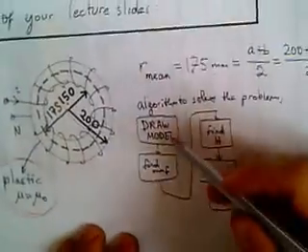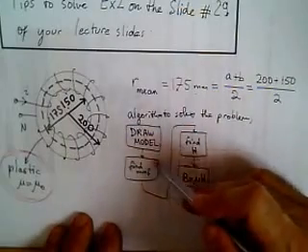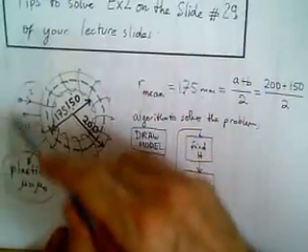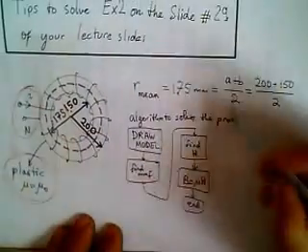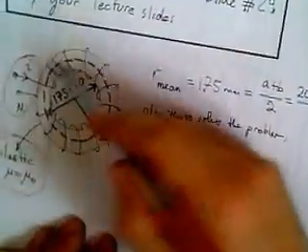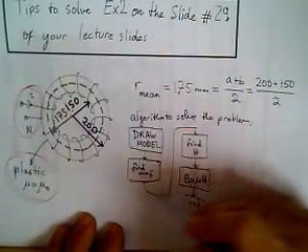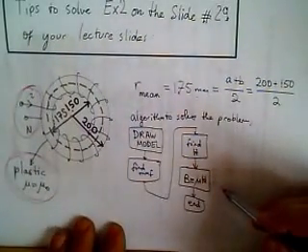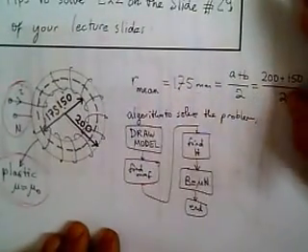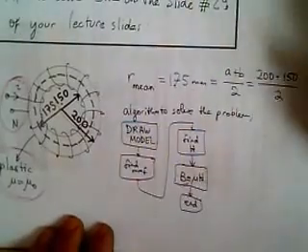So the philosophy is the same. First we draw a model, then find MMF. MMF is found by using these two parameters. Then H is found by using the path length. Then B is found from H, and we end the problem by introducing the result found as magnetic flux density, or B.